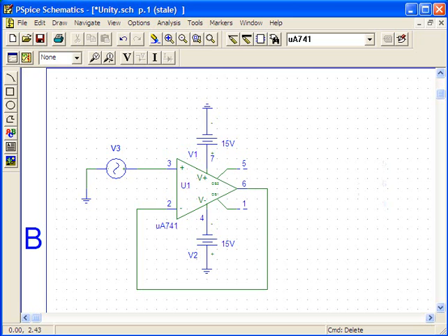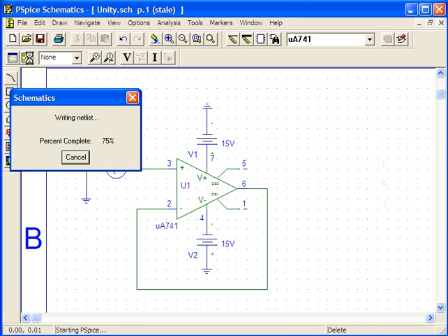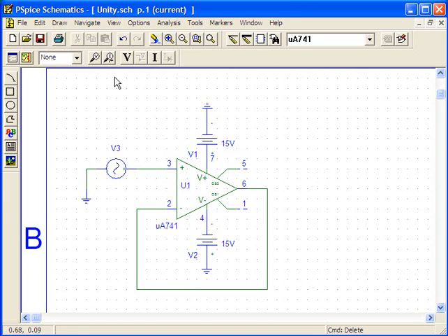Now let's get to the exciting part, the simulation. First, click on the Simulate button. We can see that there's no error message on simulation. However, at the same time, there's no signal showing up on the simulation window. To call the signal out, we need to enable transient analysis.